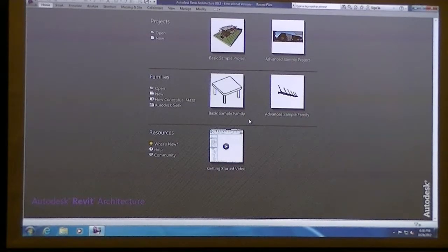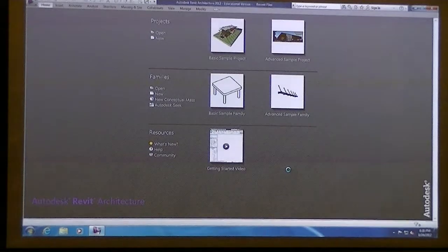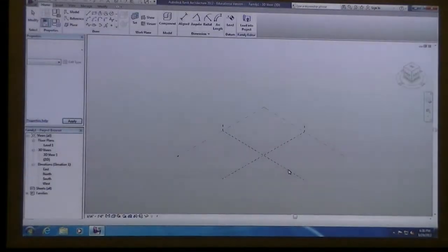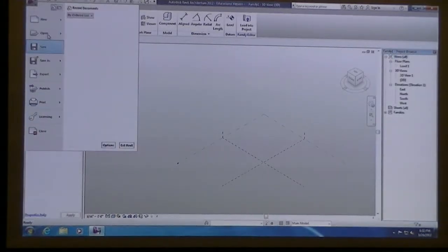Issue number 1, anybody? Can we increase the amount of points we have after we already did it? If the curves need to be tighter than they are. Yeah, unfortunately, the curves are all connected by the amount of points that you first put, and you can't just add in another point. So you have to dissolve. There's a dissolve button. Let me load up Central Mass here. And you have to dissolve it and keep all your parameters. So if I actually load up one of my curves.